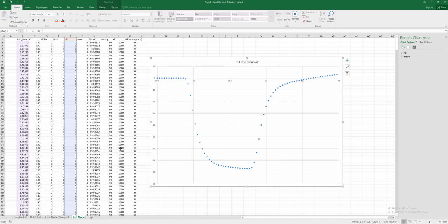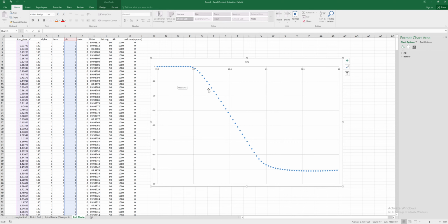So if we go back to phi here, really what they feel is this constant change in the bank angle given some aileron deflection. If they want the bank to be changing faster, then they increase the aileron deflection, right? Or if they want it to be slower, they decrease it, and they feel like it's almost one-to-one. And what they're not really noticing is this transient right here, which is the roll mode, which is the time it takes, from when they deflect it, to get up to a constant rolling rate, or a steady change in our bank angle, roughly. So anyway, that's the roll mode.